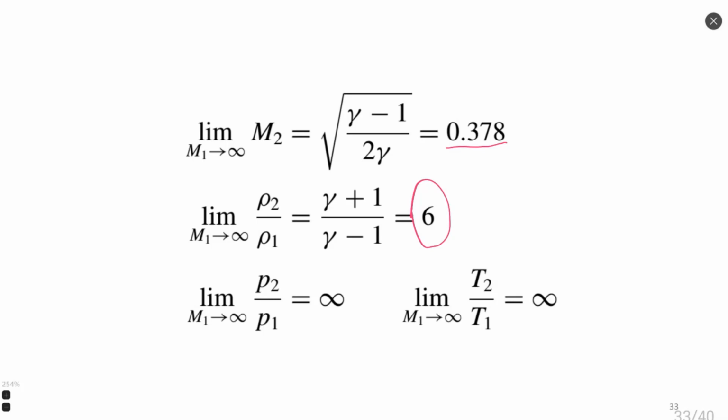When flow re-enters from space, it depends on altitude and on many factors. For very rarefied atmosphere, Mach number could reach even 50 times more than the speed of sound. But in this case, since pressure is almost 0, we have no drag, and we can reach such high velocities of re-entry at high altitude only.